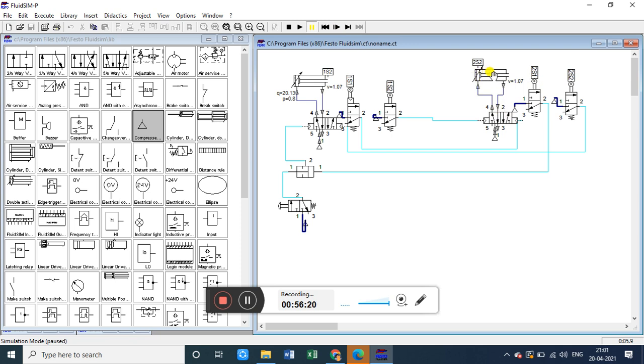Now this piston rod has started its forward journey, meaning it has left the 2s1 position, so 2s1 is unpressed, and the rod end is in between 2s1 and 2s2. We can say the piston is in between 2s1 and 2s2, but it's moving towards the right. Because of this movement, this one becomes unpressed, and because of that the upper side block becomes inactive and this block becomes active, because of the spring.